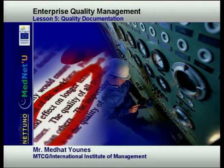Also in this section, any items of equipment which have been subjected to overloading or mishandling or have been shown by calibration to be defective should be taken out of service, clearly labeled and stored in a specified place until they have been repaired. Calibration of equipment should provide reference to standards of measurement held that are used for calibration only and for no other purpose. Reference materials, where possible, should be traceable to national and international standard reference materials.